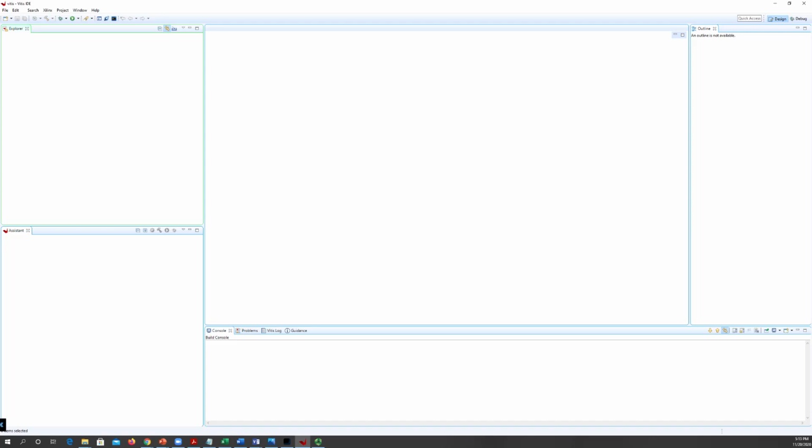But we'll want to target a bunch of the hardware devices on the board, buttons and switches and LEDs and the like. So to make all that stuff available, and also to configure the ARM processor with the parameters that are on the circuit board, things like the clock frequency and the amount of memory on the board, we have to tell it. The ARM processor can't know about that unless we tell it. And the Vitis tool set can't know about it unless we tell it as well. So to do both things, to set up the ARM processor for use and to program the FPGA so you can get at all the onboard utilities, you can do that in one step.